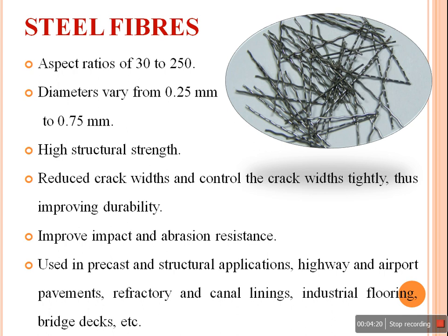Although both these methods provide tensile strength to the concrete members, they do not increase the inherent tensile strength of concrete itself. So the idea of fiber reinforcement, or providing fibers in the concrete, is to increase the inherent or internal tensile strength of concrete itself, rather than providing some other members to resist the tensile stress.